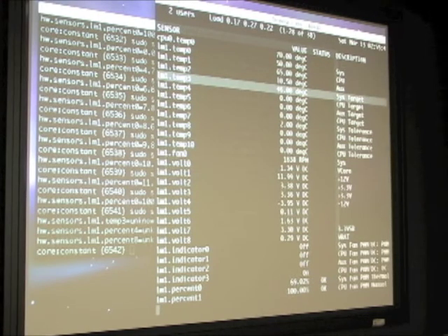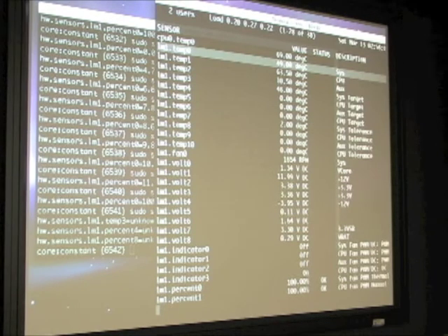So right now in the thermal cruise mode, you can see that the value that the system decides to run at, that the fan thinks that it should run on, is 100% duty cycle, because the system target temperature is 46, and the sensor reading is 49, and the tolerance is 2. So when this value goes below 44, then it may turn to a lower level.